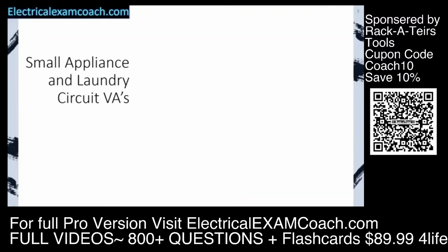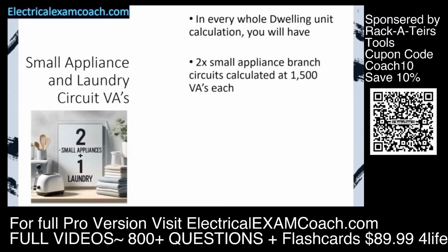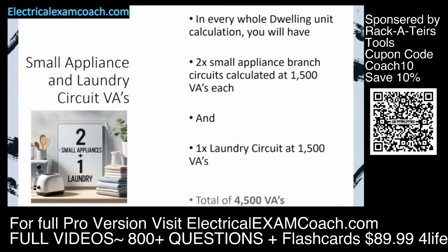Now that we've learned about our 3 VAs per square foot, now we have to learn about what's called our small appliance and laundry circuit VAs. In every whole dwelling unit calculation, we're going to have 2 small appliance branch circuits calculated at 1,500 VAs each, and 1 laundry circuit calculated at 1,500 VAs each, for a total of 4,500 VAs.